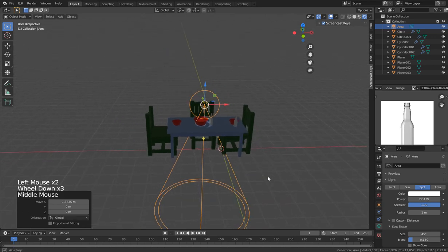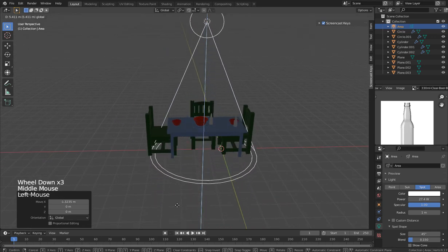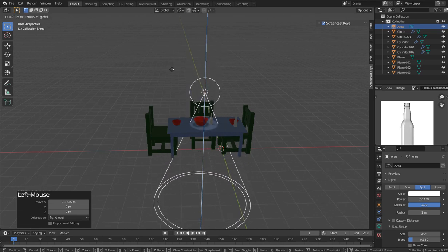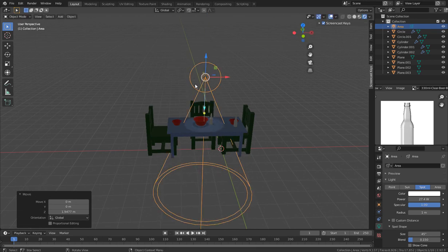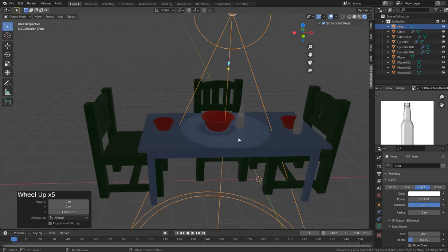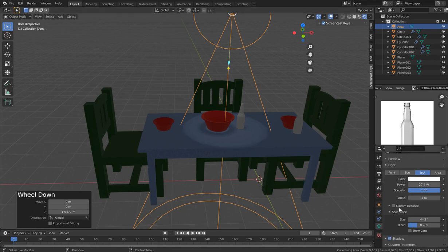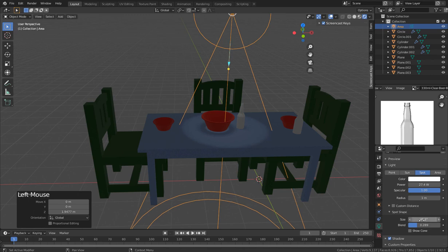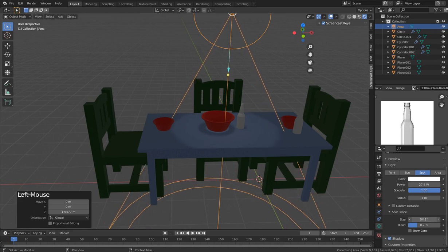Okay, so with the spotlight, this is how it is, and just like it's saying spotlight, so it's lighting a particular spot, and you can see it's defined properly here. Look at this one. And with the spotlight, we have the size of the outer cone of a spot, which largely controls the circular area a spotlight covers. This slider in fact controls the angle at the top of the lighting cone and can be 1.0 to 180. So as you can see.